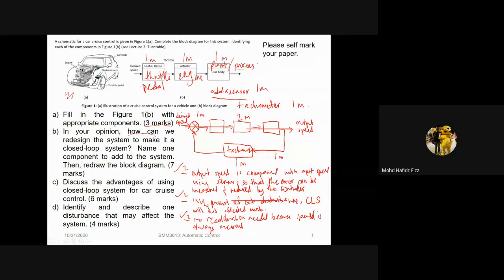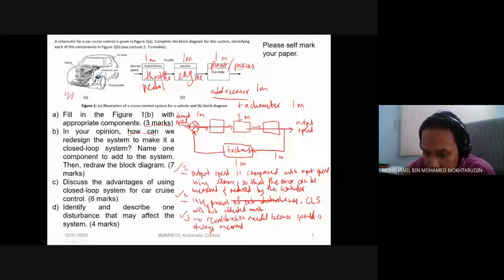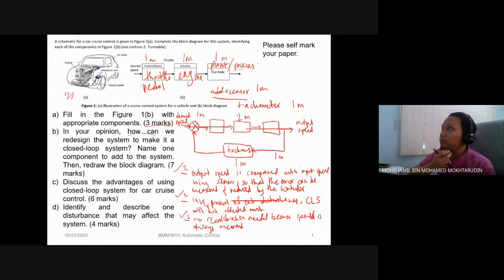Oh okay, if the answer is that the sensitivity of the system may be made small to make the system more stable. Stability can also be a point, but no, because closed loop has problems with stability compared to open loop, as in the table the other day. Because open loop doesn't have any stability problems, meaning you don't have any vibration problems in open loop system.